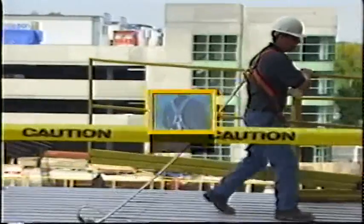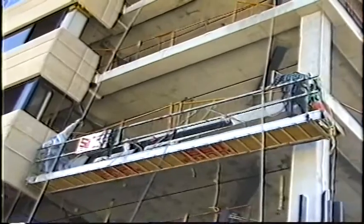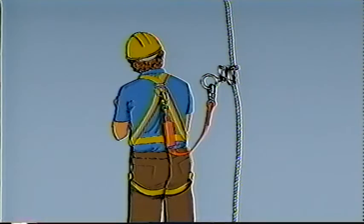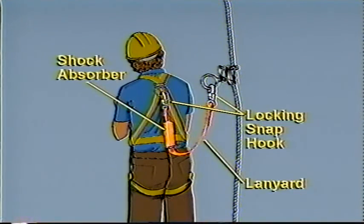When fall prevention is not practical, you must use a fall arrest system. A fall arrest system doesn't prevent a fall, but it limits a fall once it occurs. The system must be set up to keep a worker from striking any object or surface below. A typical fall arrest system consists of several engineered and certified components, such as an adjustable full-body harness with a built-in attachment point for a shock-absorbing lanyard.